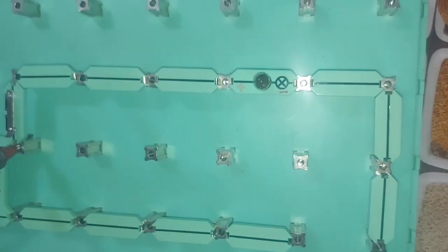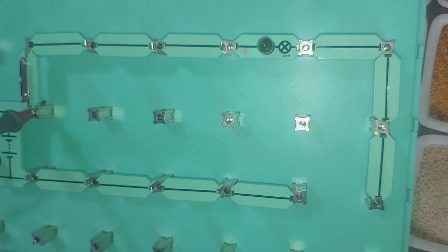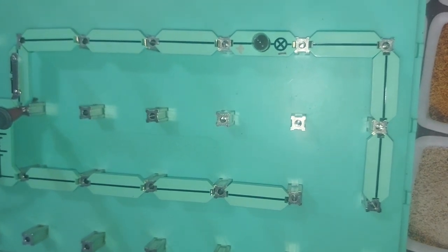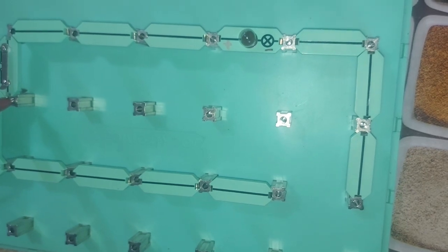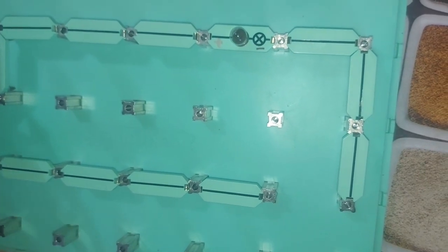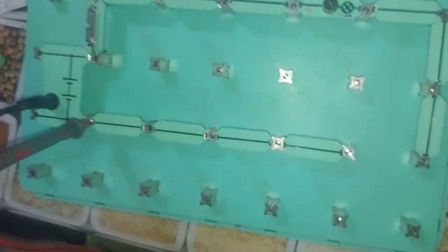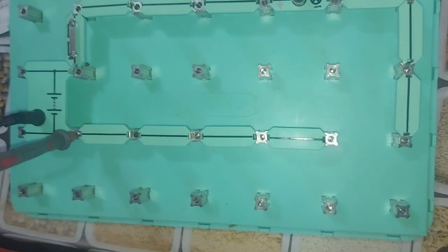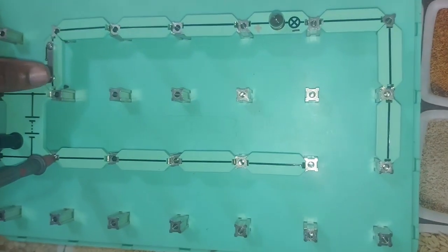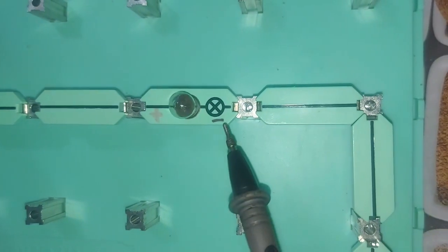Because mind you, it's a short circuit. We are looking for where the voltage is. That's where the short is. We couldn't find the voltage on the positive side, so it is not there. So when we come here, that's the ground side. Okay? When we come to the ground side, I close the switch. Remember, ground starts here.